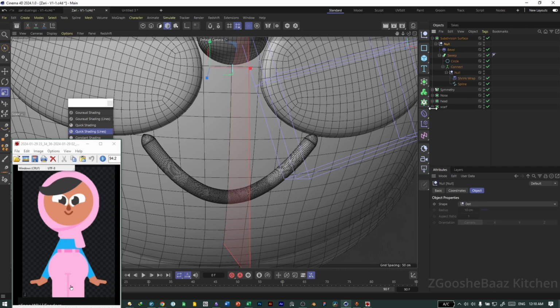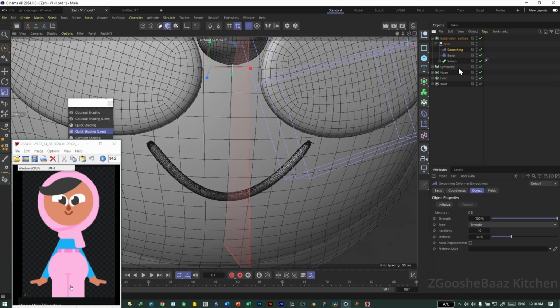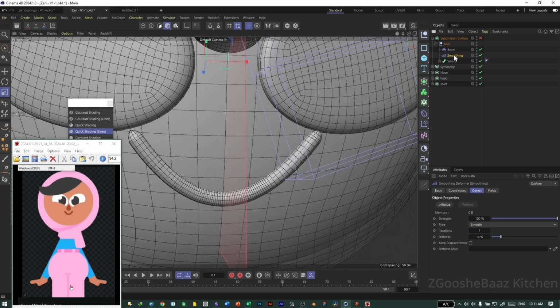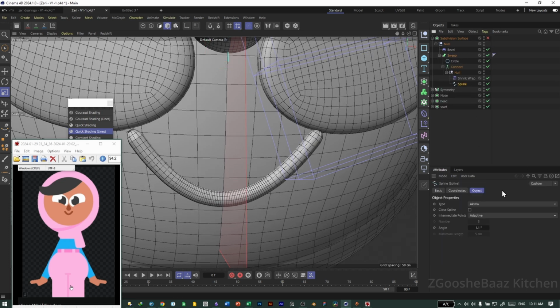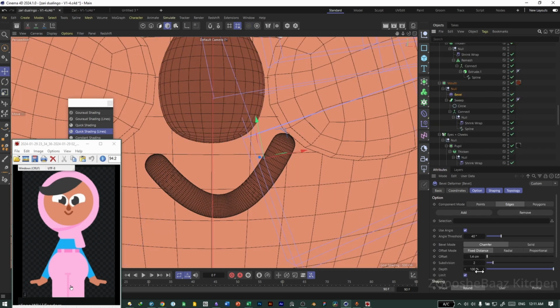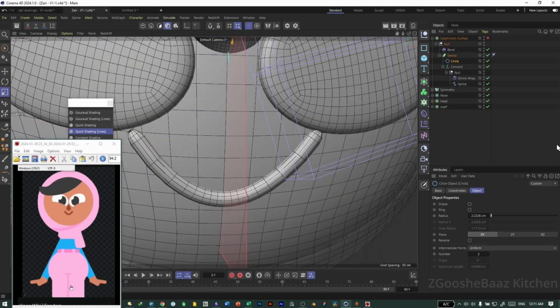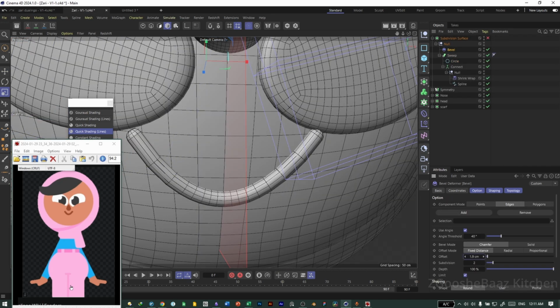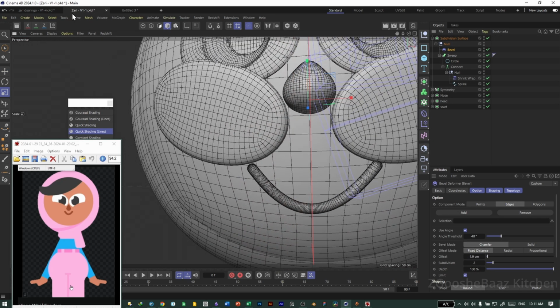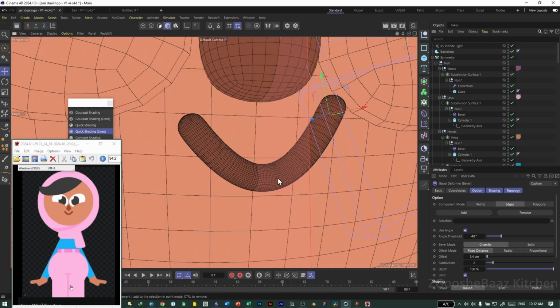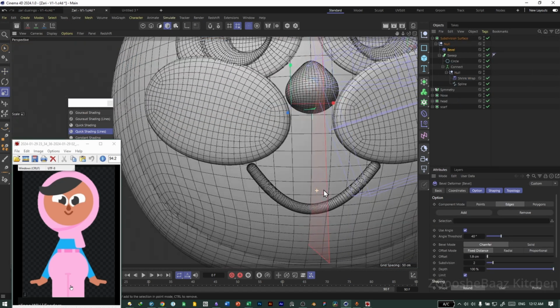How about putting a smooth modifier also here after bevel? It's not working as we like it. Change the iteration. No, I didn't like it. Let's change the value for this to something like 7. For the circle, 2 I think is okay. For the bevel let's use 104, 104, let's offset in 2. And I saw these values from my first file because I played with the values a lot here.